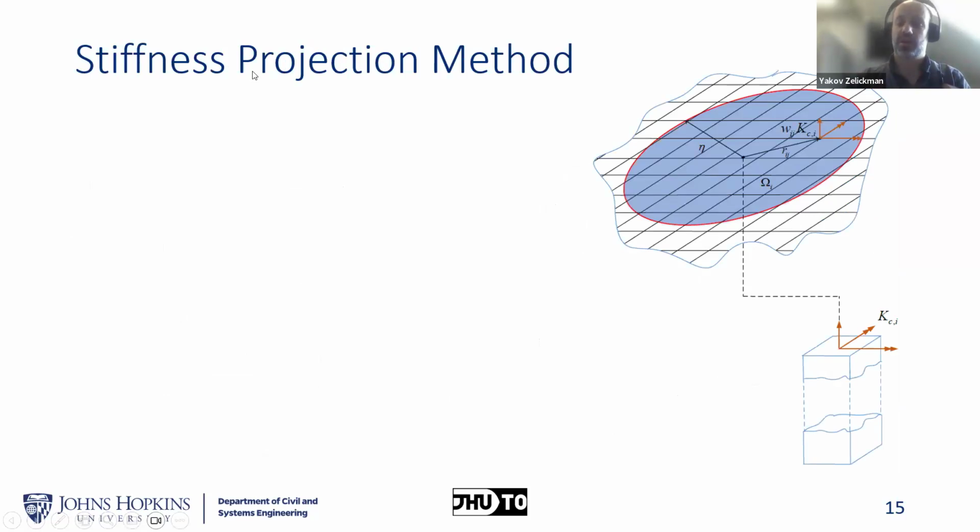Next, once we have the model of the plate, we want to parameterize our supports so they can move freely in the entire area of the floor. The problem is that if we connect them to nodes, in every iteration we might need to remesh the floor, which is computationally expensive, or we would be restricted to very small changes in the design.